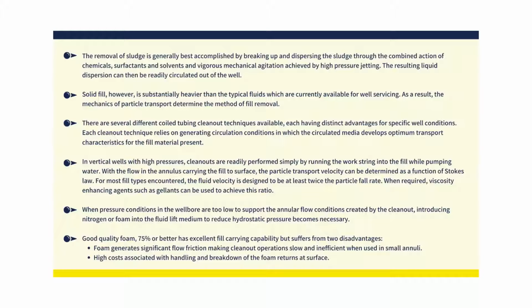Good quality foam, 75% or better, has excellent fill carrying capability but suffers from two disadvantages. Foam generates significant flow friction, making cleanout operations slow and inefficient when used in small annuli. And there are high costs associated with handling and breakdown of the foam returns at surface.